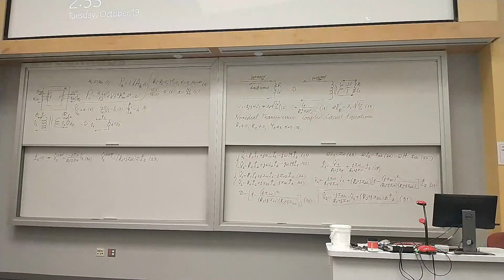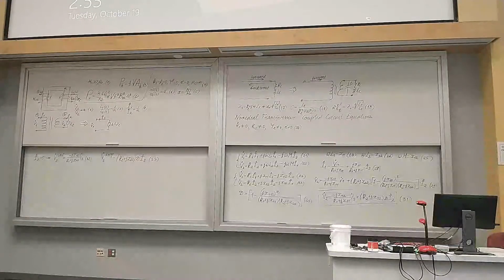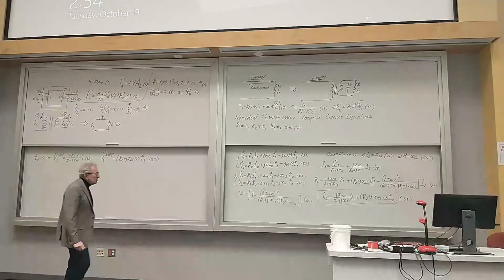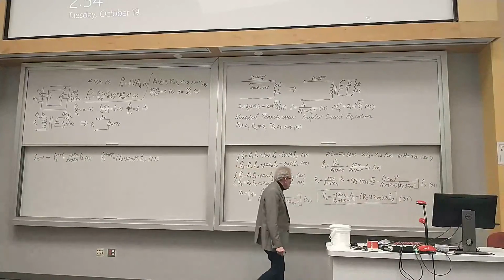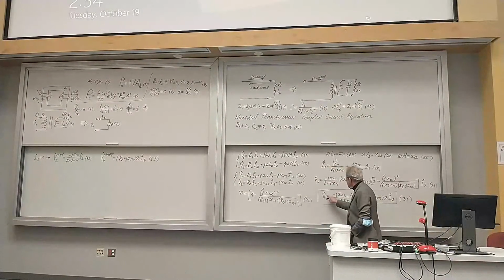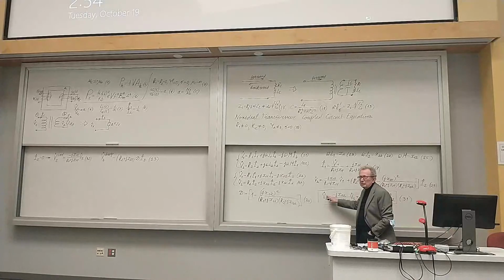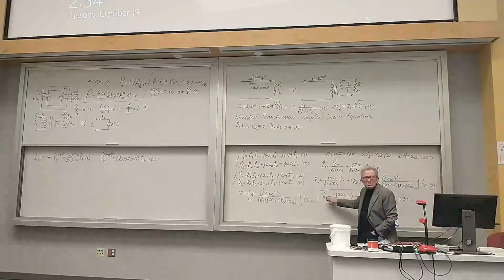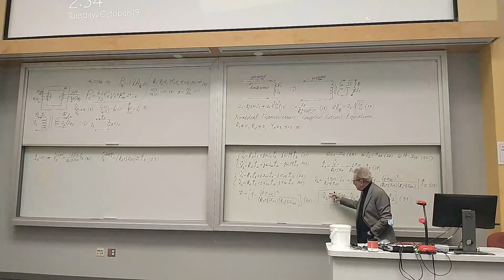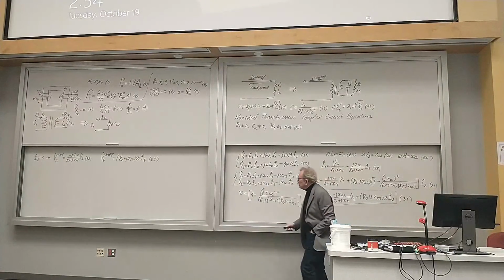But in life, whatever you will get, you will have to pay a price for this. What will be the price for small d? The price for small d will be due to the situation when accidentally we will have short circuits of the secondary winding. So we will consider the short circuit of the secondary winding. What the short circuit of the secondary winding means is that this voltage is equal to 0. It's a highly undesirable regime, that this voltage is equal to 0.